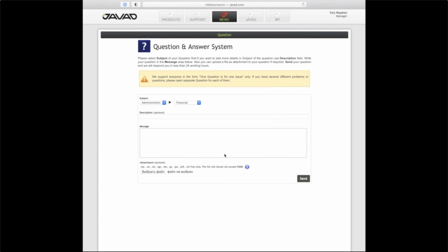David Stilwell is asking, we need more clarity of when WGS84 and origin indicate, when looking at the point properties, what coordinates are being displayed. Okay, thank you for the questions too. That corresponds to the previous questions. Then the base station transmits not in ITRF or WGS84, but in other coordinate systems.